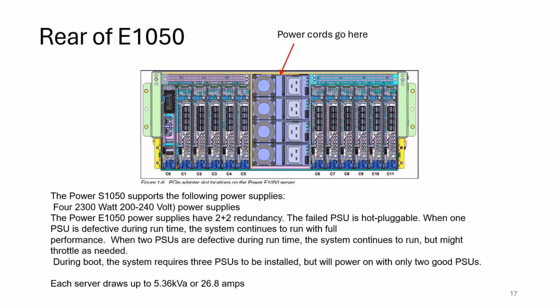During boot, it requires 3 working PSUs. It will power on with only 2 of them. So again, you need to connect all 4 power supplies to make sure that things will work normally.